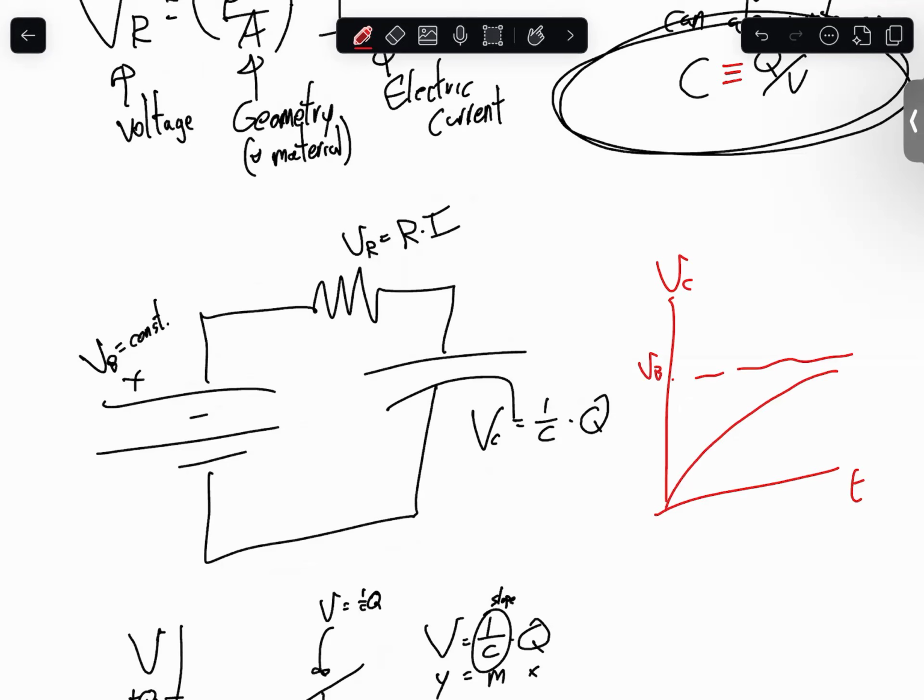If you've got a little ripple on your DC signal, you've got a power supply, but the voltage is sometimes a little more or less than what your average wants to be. When you supply more voltage, charge goes onto the capacitor instead of into your circuit. When you apply a little less voltage, charge flows off the capacitor to keep your circuit level constant.